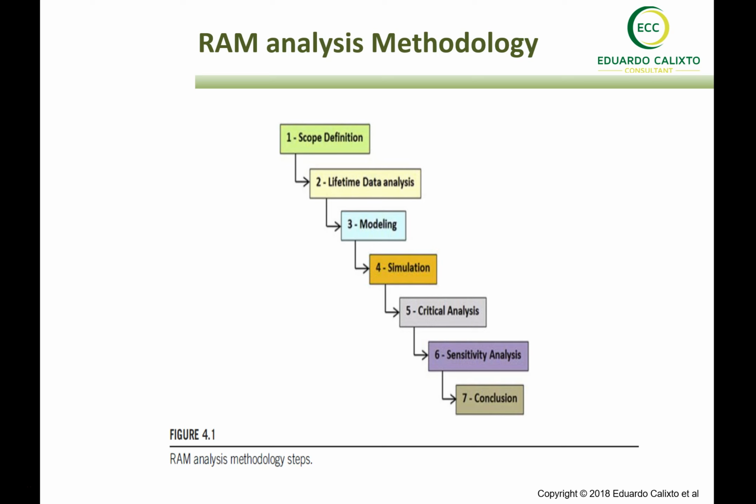Some important recommendations about the simulation: we need to define the proper setup for the simulation, the units of time that you're going to use need to be clear, and we need to be careful with the number of simulations, because if we have a huge model and we put a high number of simulations, for example 1000, in some cases it's better to put 500, which should give similar, confident results, and not take more time by running 1000 simulations, for example.